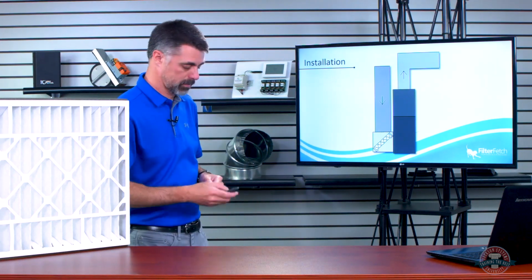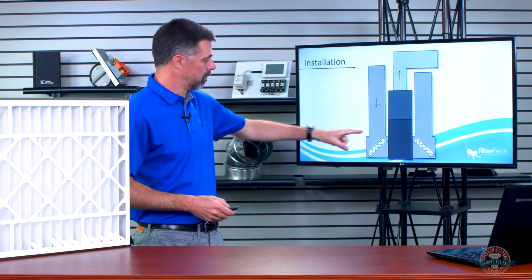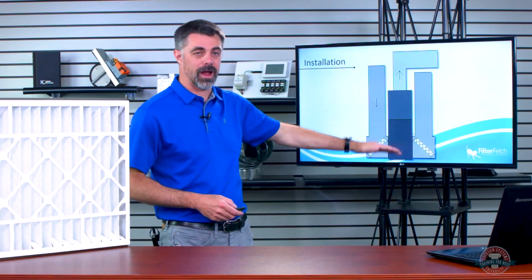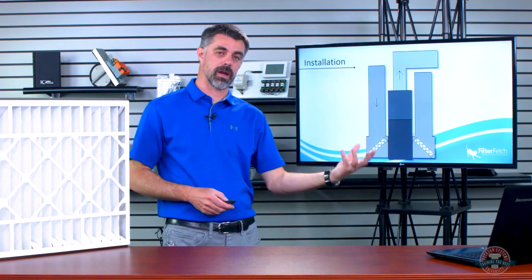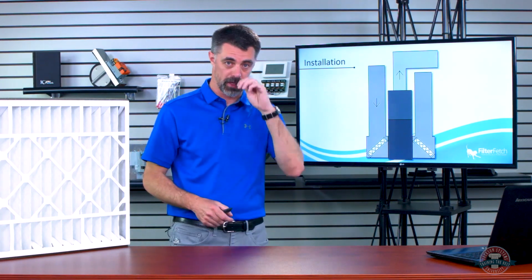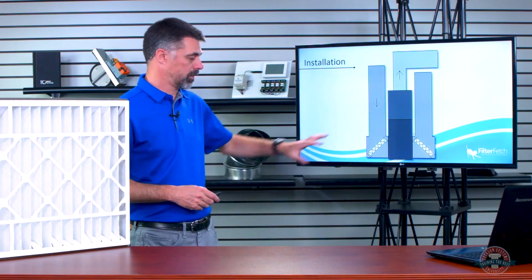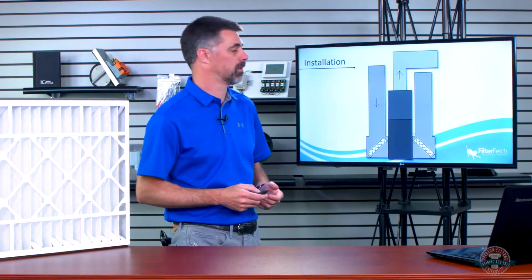All right. And again, if you need more air, put two boxes on. Again, that is if you've got height limitations right here. We can't put a box underneath to feed the bottom of that furnace. I might have to come in both sides. So again, more options there for you. These are all configurations that I've used and installed over the years depending on what was necessary with the job.